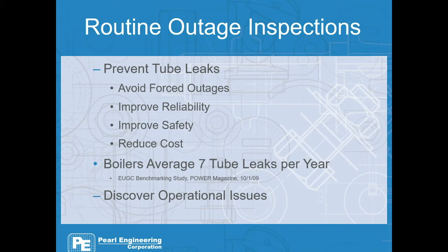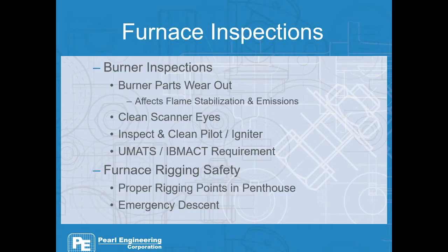Sometimes you can discover operational issues you didn't know you had, or you can find the root cause of your issues. Say you've got pluggage in a duct, your ID fan was working harder than it should. You're not going to know that unless you get inside and take a look.